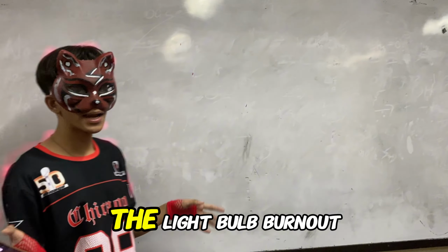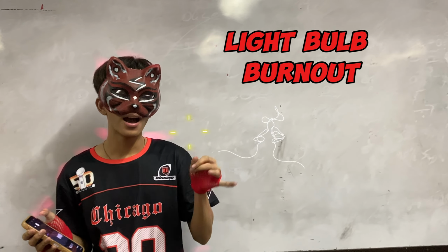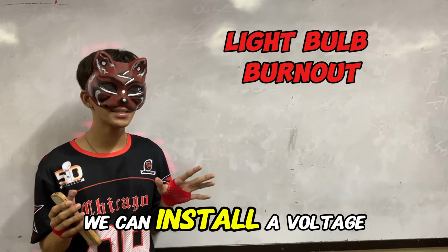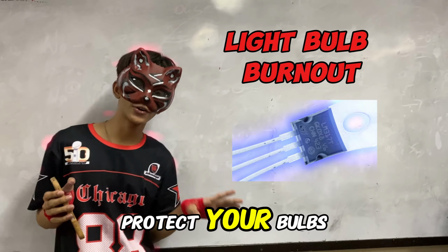Now let's move on to light bulb burnout. Light bulb burnout is commonly caused by voltage fluctuations, poor connection, high temperature, and frequent switching. To decrease the chances of light bulb burnout, we can install a voltage regulator or surge protector to manage voltage fluctuations and protect your bulbs.